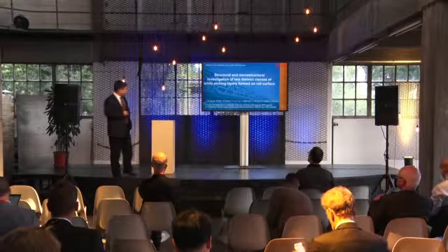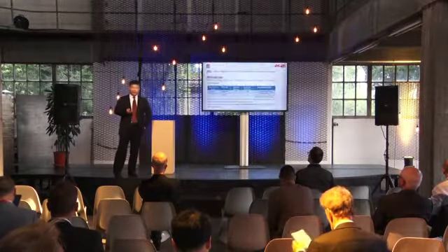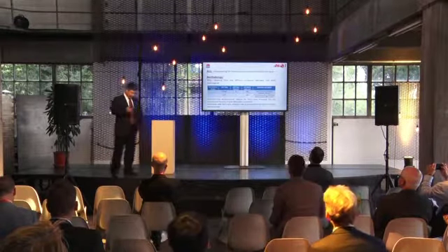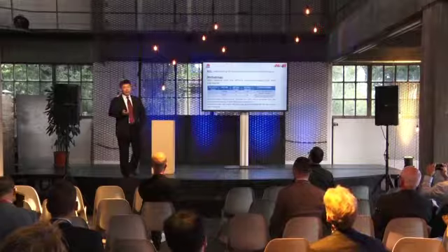Today, I would like to introduce a joint research work between the University of Wollongong and Sydney ETCHING, Australia. This joint research work focuses on the white etching layer. We try to identify if different traffic conditions can generate different types of white etching layer, what is the formation mechanism behind the white etching layer, and as a result, whether the white etching layer contributes to squat or stud formations.